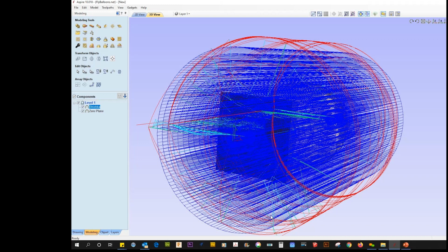If you cut in the levels, you would never stress that bit out as long as you cut in those levels. If you do a full depth engage, that's when you come into a problem of stressing that bit out, because when that rotary is turning, you have the bit cutting, and the rotary is actually turning into that bit. Either it's going to turn into it or it's going to turn into the backside of that bit, and that's going to automatically put that load on that bit regardless.